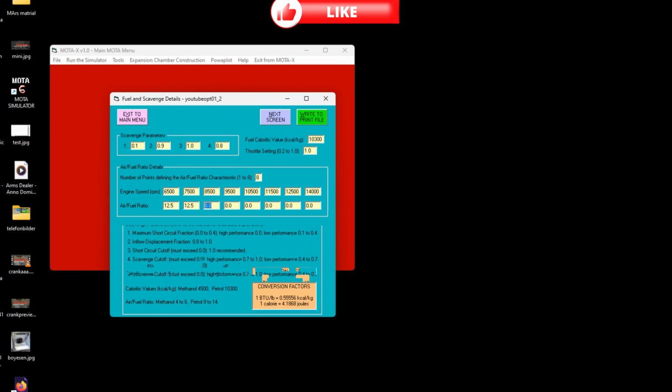Now it's probably in this region the pipe starts to build some power and boost. So I'll use 12.2 as it pulls harder in the power jet. 12.2 and here 12, 12, 12 and 13, because with the power jet I can actually make this big change.